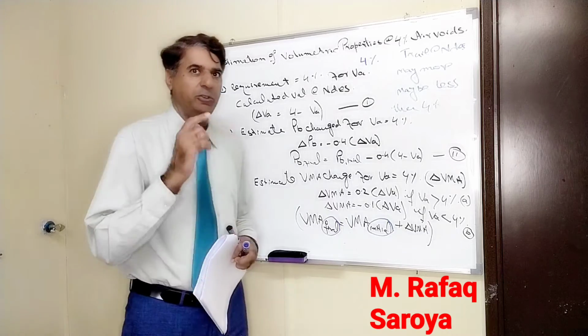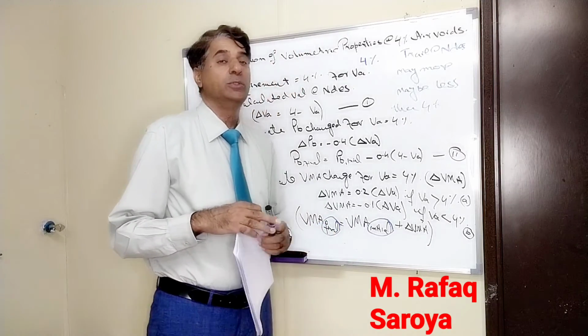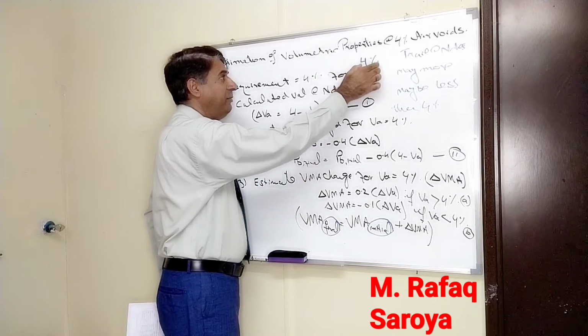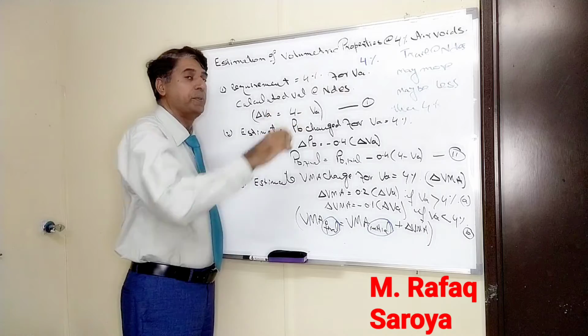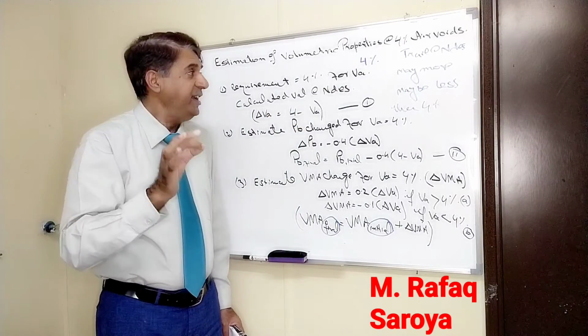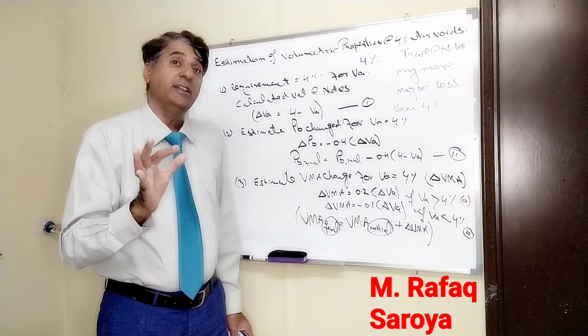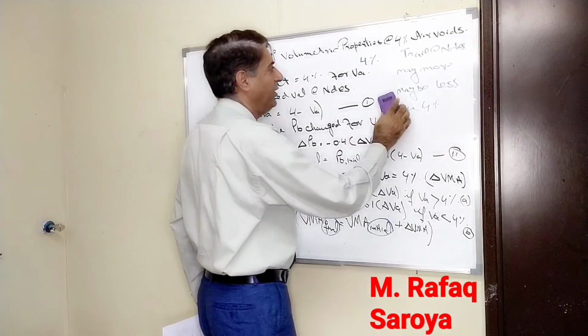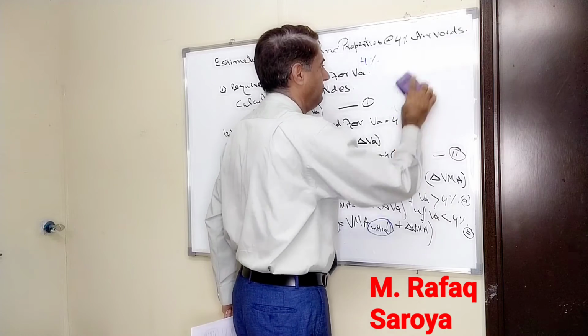But here I would like to tell you one thing. When this VMA is changed, when our air void content requirement is 4%, then it is natural that VFA will also be affected. So here I would like to give you the result for this VFA.